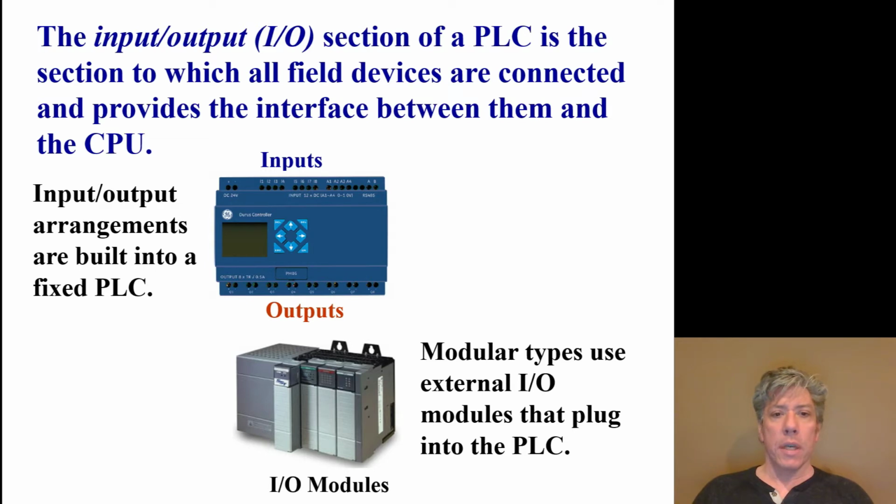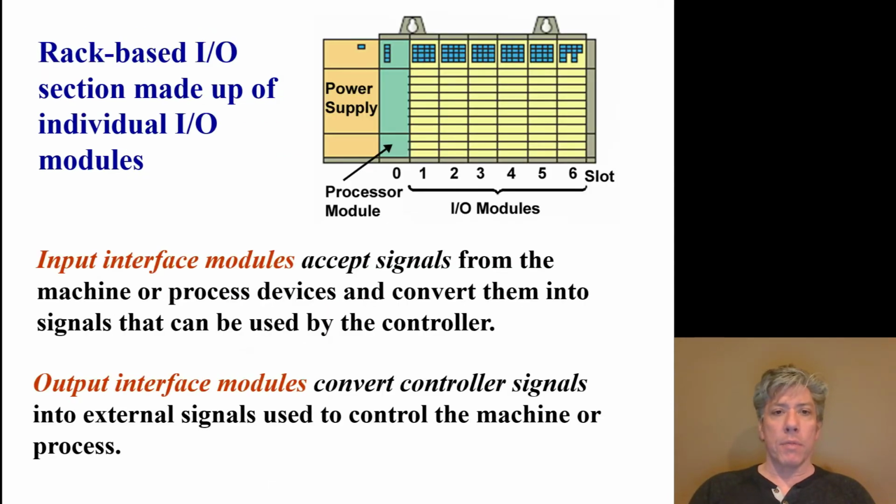of the PLC. Some PLCs are set up where they only have so many inputs and outputs, and these are terminal points that you can connect wires to, and some are modular where you can add or remove or change out various input-output types of modules.